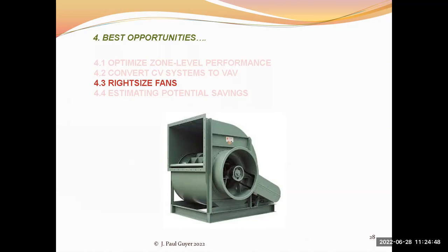Some of the premium efficiency motors operate at slightly higher speeds than the motors they replace. Because a fan's power consumption increases in proportion to the cube of its speed, it's important to compare the nameplate speed of the existing motor with its premium efficiency replacement motor.